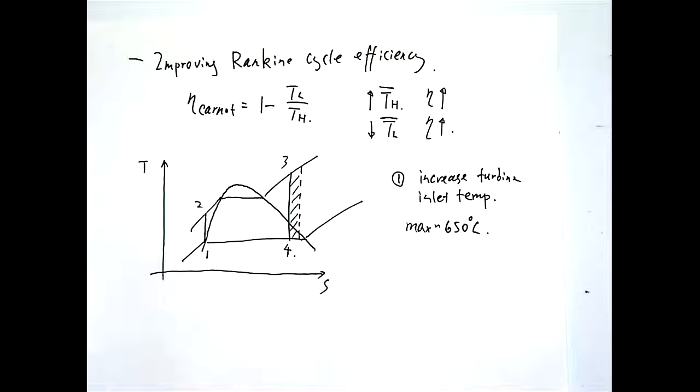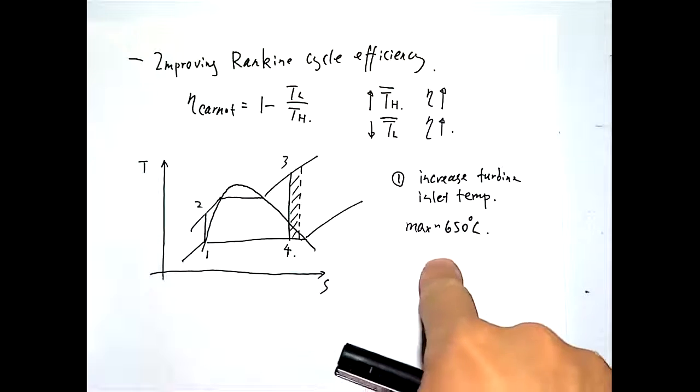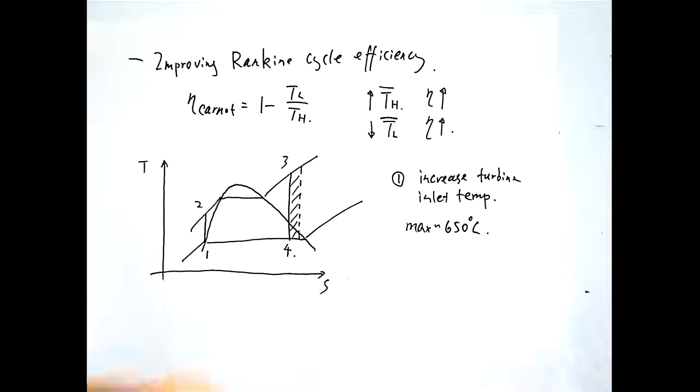It's related. If you consider how the combustion or heat transfer happens here. A gas turbine is an internal combustion device, right? The gas is directly being burned, so it absorbs basically all the heat except the heat loss. So it can be raised to a very high temperature. But for a steam turbine, steam is not directly coming from the combustion, right? Steam must be heated by something happening outside the steam tube or the steam generator in order to transfer the heat to the steam, right?